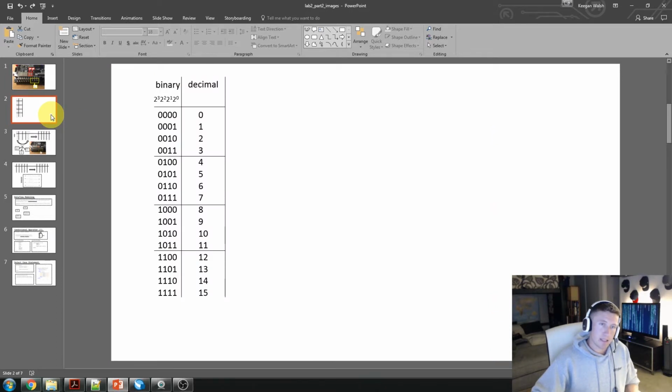So let's make sure we do that. And also, in the previous lab, I mentioned we had these don't care conditions. So you might be saying, well, let's just use those don't care conditions for this lab. Well, you have a few problems by doing that. How do you control the most significant and the least significant bits going to each hex? So okay, we've got to account for that. And the other problem is we didn't even consider those in our decoder design, our 7-segment decoder design. We only coded that to output 0 through 9. So instead of going back and redoing that whole thing, let's just use what we've already designed and hook things up a slightly different way.